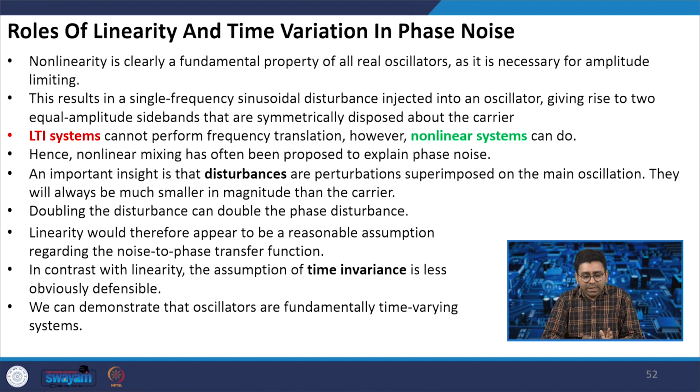The important insight is that disturbances or perturbations superimposed on the main oscillator will always be much smaller in magnitude than the carrier. And when we double this disturbance, it doubles the phase disturbance. So, it is like when we are considering the linear case, in terms of the phase noise.